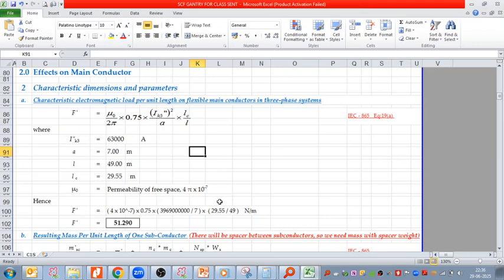Will this be discussed or is it meant for general understanding? General understanding. We take the three-phase short circuit current, and considering it, when a three-phase fault occurs, how much force comes, that force we are calculating. If you consider three-phase fault, line to line force, and line to ground force, the highest force is from the three-phase fault. That's why this one is considered.